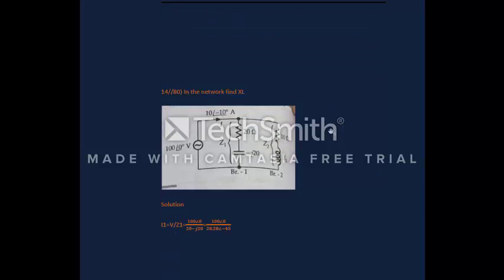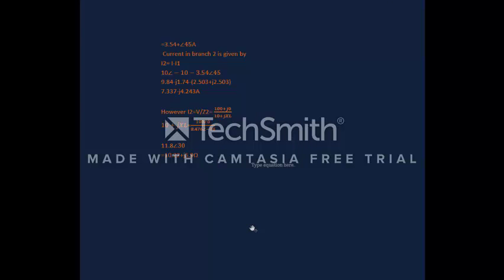Now let's see the last question assigned to me. In this, a network circuit is given, and it is asked to find XL, this inductive reactance. So let's see the solution. I1 is equal to V upon Z1, which is 100∠0° upon 20 minus 20j, equal to 100∠0° upon 28.28∠-45°, which is equal to 3.54∠45° amp.